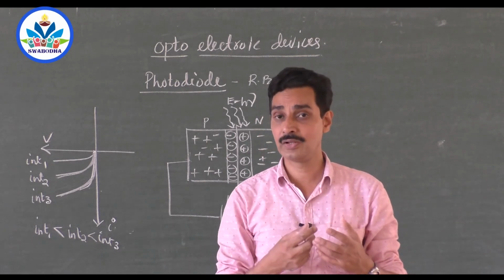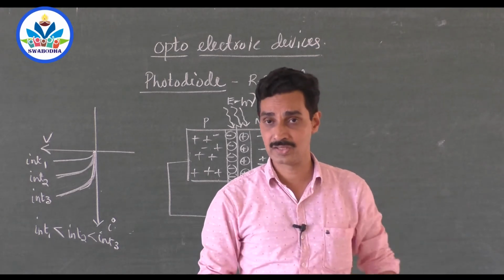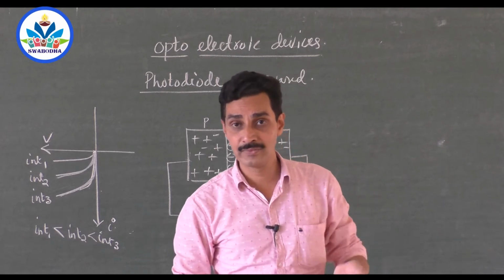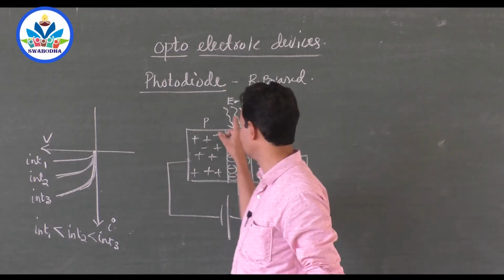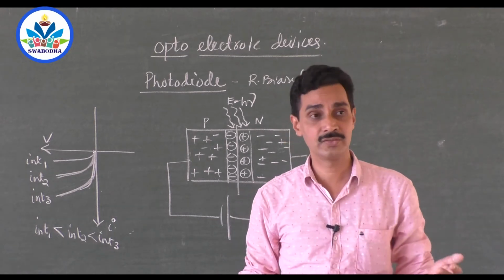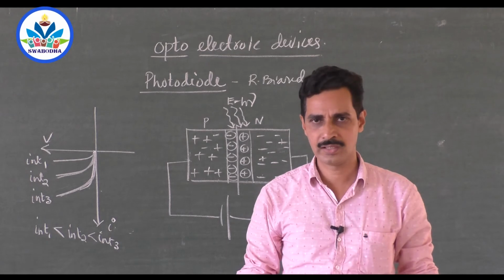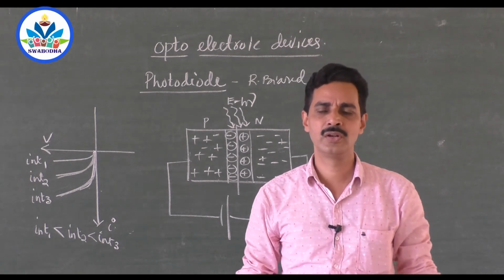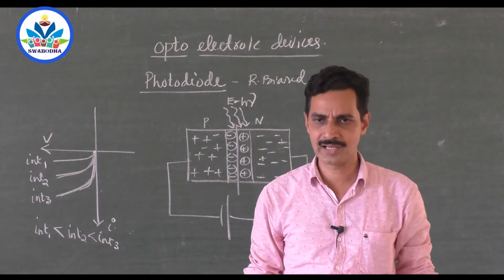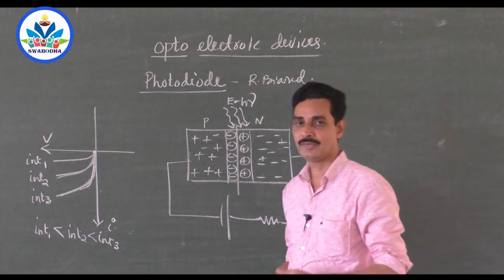The light will be falling on the photodiode, and the photodiode will convert that light energy into electrical energy. If that electrical energy is very weak, meaning the intensity of light is very weak, it gives the signal and the flash switches on. So we have automatic switching on and off of the flash. Nowadays you need not switch on the flash, you need not check whether the light is enough or not. Automatically the camera switches on the flash.